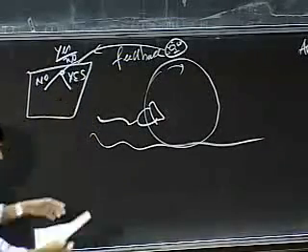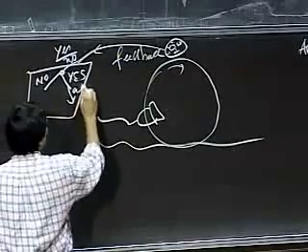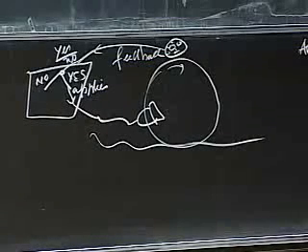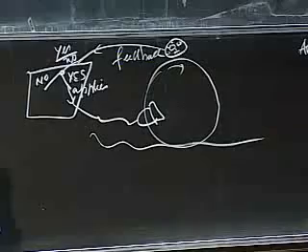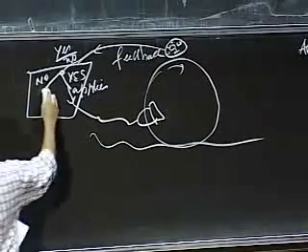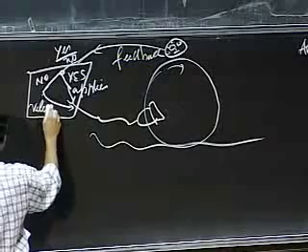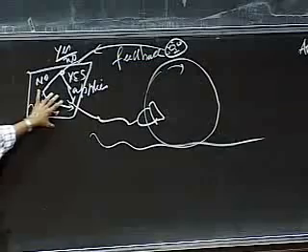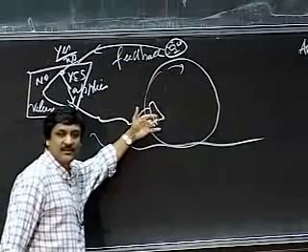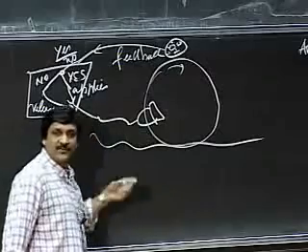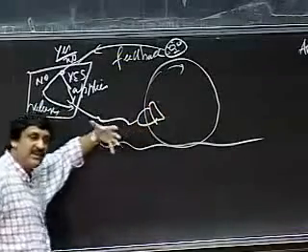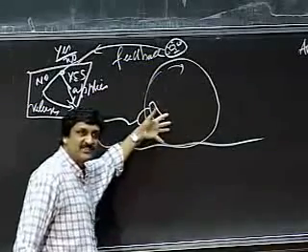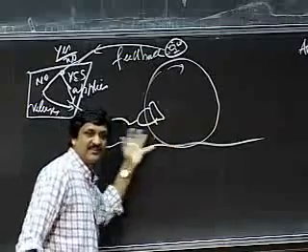If it's yes, then what this does is it applies the brakes even more strongly. It's turning, so I can apply more brakes. But if it says, oops, it stopped turning, the controller simply releases the brakes. As soon as the controller releases the brakes, the tire tends to loosen up a little bit and starts turning again. So this way you're constantly keeping the tire in its region of critical friction so that it's constantly moving, and static friction applies to how hard you can brake. And it doesn't start skidding.